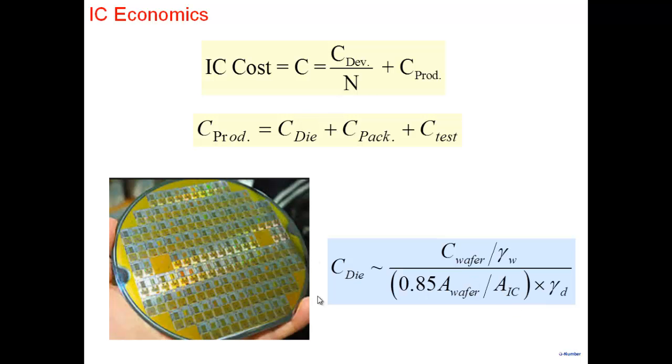And while you are making the wafer, you go and probe each particular die. There's some simple test that you run, this is not that particular test that I'm talking about. This is the wafer probe test. On the wafer itself, you probe each die, and you know which dies are working and which are not working. So this is the yield. How many dies are working?